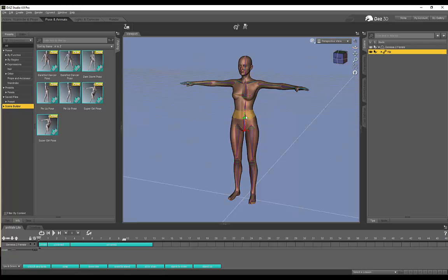Now it's very important, if you're combining multiple animations, you want to fix that hip pivot point only at the end, once you're 100% sure that you've got all your animations in place and this is what you want to use. Because I've noticed if I edit that pivot point right now by the hip into the correct position and I import some new data, it tends to mess it up guys. So just do this right at the end.